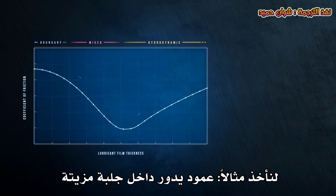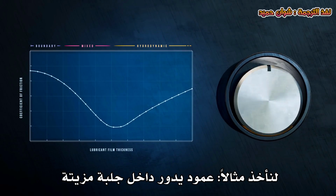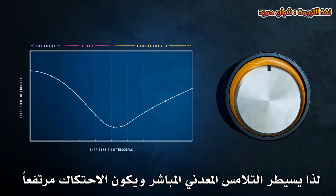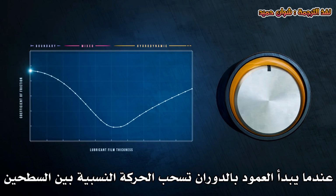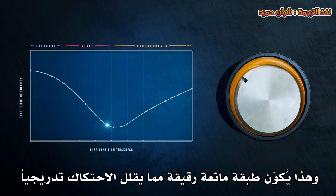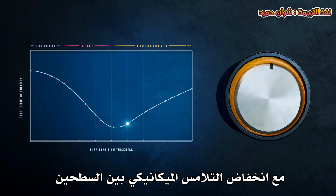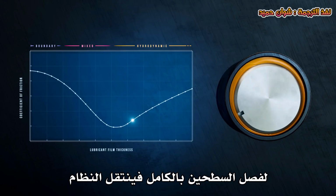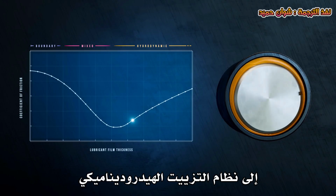Consider a spinning shaft inside a lubricated sleeve. When the shaft is still, there's no motion to draw lubricant into the gap, so metal-to-metal contact dominates, and friction is high. As the shaft begins to rotate, the relative motion between surfaces entrains lubricant into the contact area. This builds a thin fluid film, gradually reducing friction as mechanical contact between the two surfaces reduces. With increasing speed, the film becomes thick enough to fully separate the surfaces, entering the hydrodynamic regime.